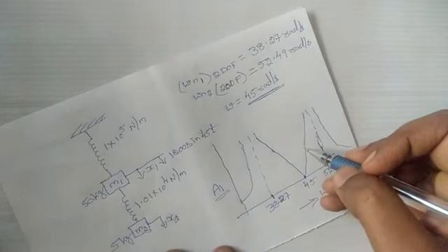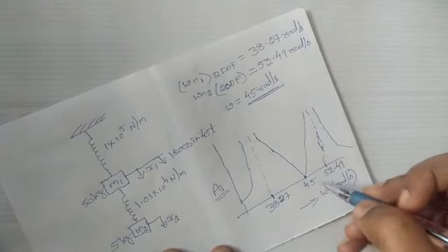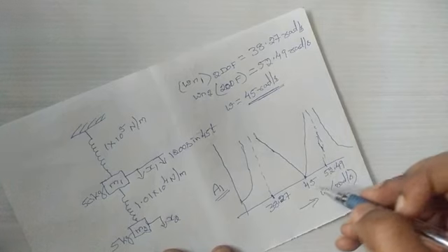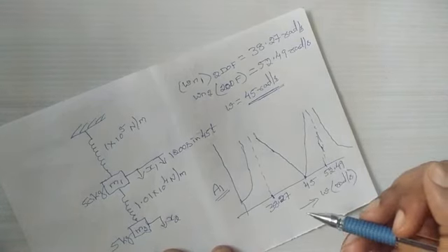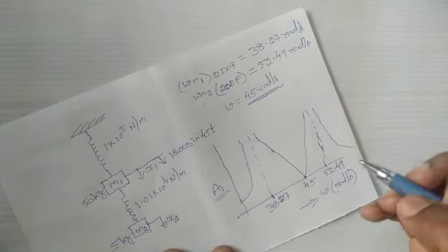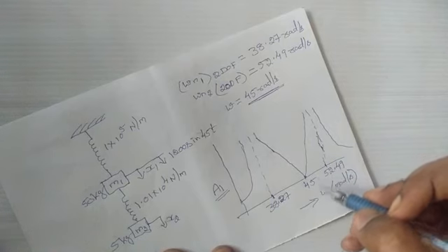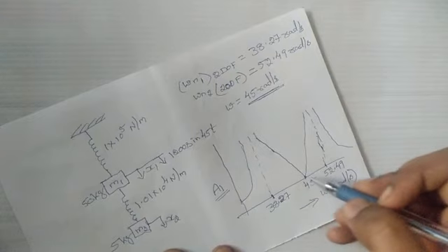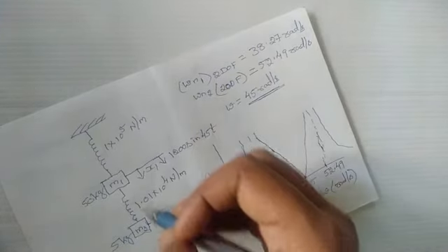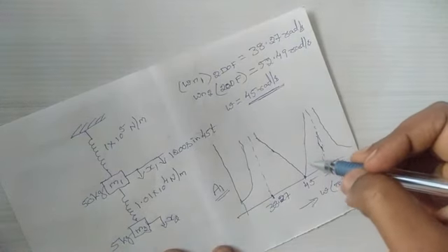So the application would be in situations where the forced frequency is not going to vary. You're going to operate at that particular frequency for which the absorber is designed. So only in such cases will you use the vibration absorber. If you are going to vary the forced frequency over a range, you cannot use the vibration absorber to absorb the vibrations of the machine. So this is what we need to understand. It's a very narrow range.